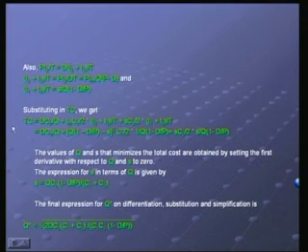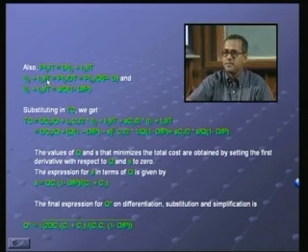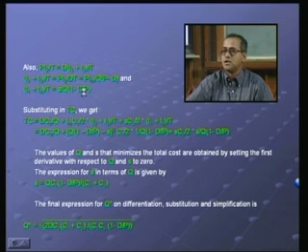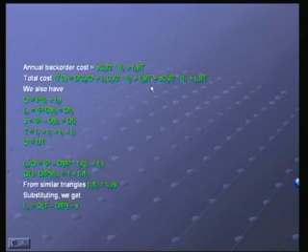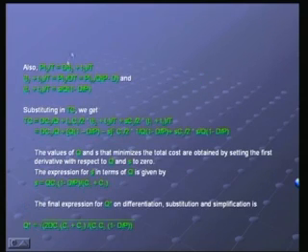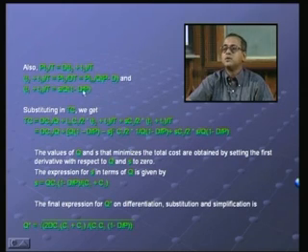And then we go back and we also get this T2 plus T3 by T is P into Im by Q into P minus D, or Im by Q into 1 minus D by P, and T1 plus T4 by T is S by Q into 1 minus D by P. We need these two terms, T2 plus T3 by T here and T1 plus T4 by T here. So, both are now written as Im by Q into 1 minus D by P and S by Q into 1 minus D by P.